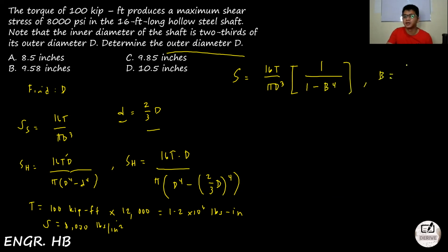That b is the ratio of your small diameter to the outside diameter. That is a derived formula. Why? Instead of typing term by term, when you shift solve on the calculator, it will fill up your calculator and may cause lag, or make shift solve take longer. This derived formula gives it directly: this is your solid, and this is the factor that makes it hollow. Later I will solve it this way, and you can check in your own scratch work that solving term by term gives the same answer. I will show you both give the same answer.